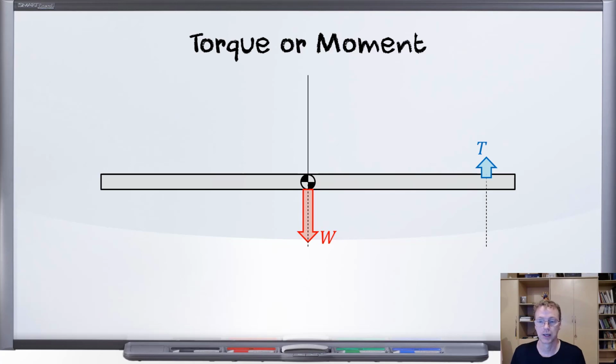Well, you may remember, and if not, here's a refresher. The moment of force is the amount of the force multiplied times the moment arm, or the perpendicular distance. So we will locate the tail some distance d_t away from the CG, and we'll say that the tail's force acts there.